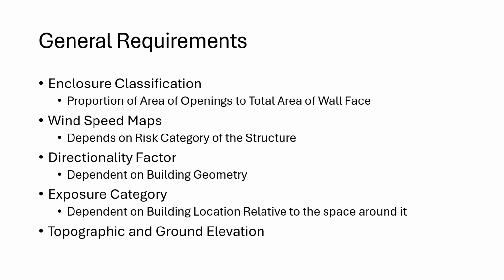So it's important to include all the factors when you have to. While you're doing your desk study of your wind speeds or your wind forces, go ahead and get all the factors beforehand instead of saying, oh, let me just work on directionality factor and then I'll go to ground elevation factor later. Get all of them beforehand so that way you have all your bases covered.